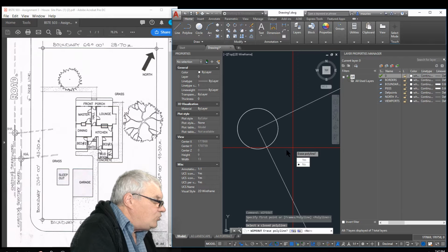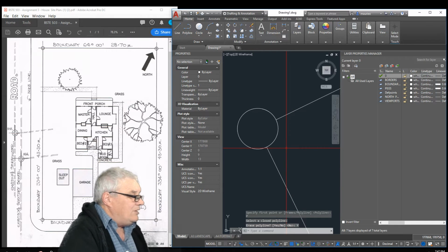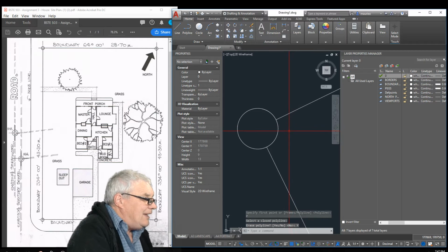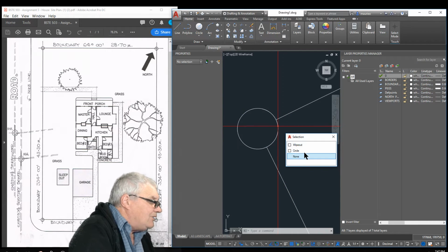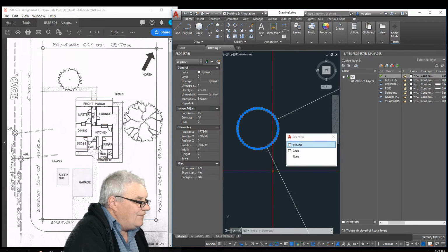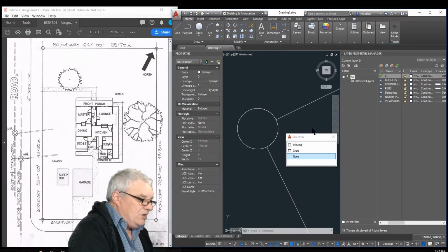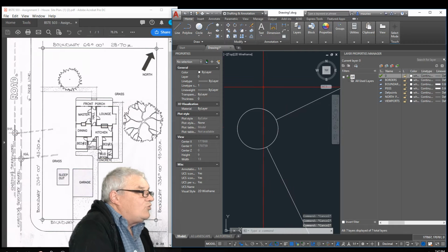And then we're going to erase the polyline, and it'll leave our little wipeout like that there. So now we see, if we zoom on there, we've got a wipeout and a circle. And you can see there that the line goes underneath the little wipeout. Pretty nifty, really.